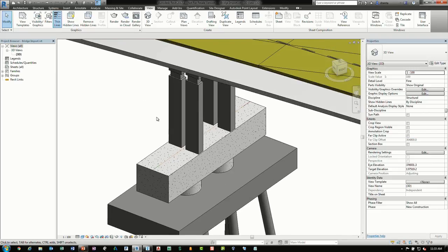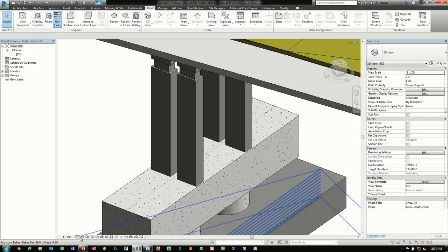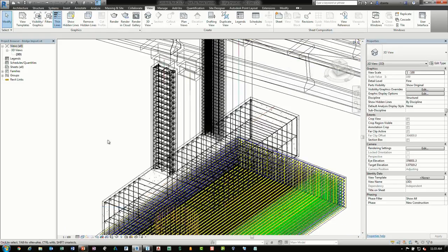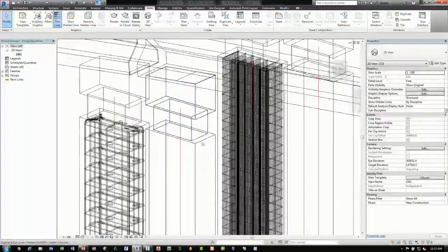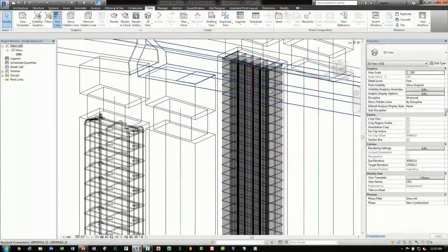The next part is looking at the rebar information. And let's head over to a wireframe view. You can see there's a couple of columns that I put rebar in here. The one on my right, this one here, is using the standard rebar commands within Revit. Again, I'm not a structural engineer, so I just threw in tons of rebar. And that process is very iterative. It just takes time. You put in a rebar, you specify things like the divisions and then the quantity and so on and so forth.